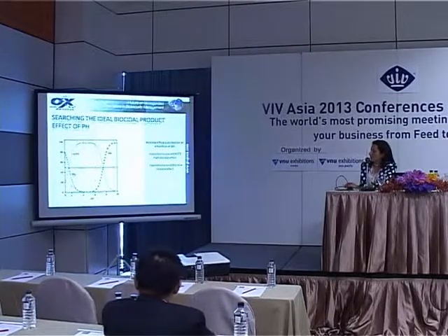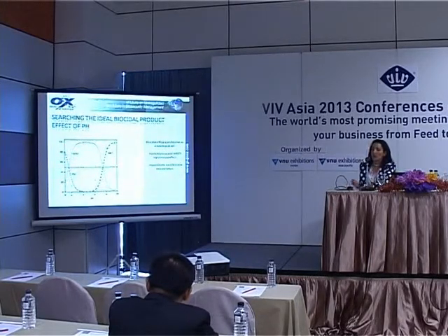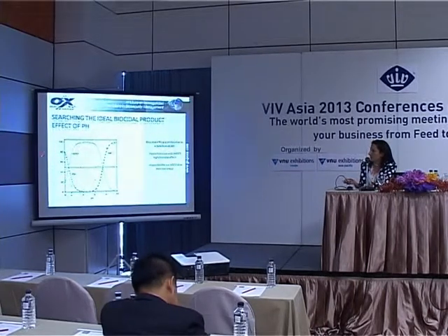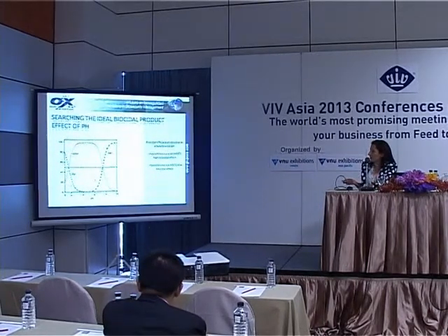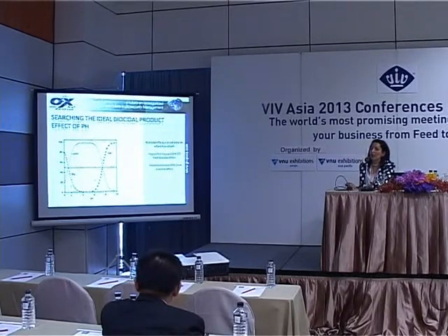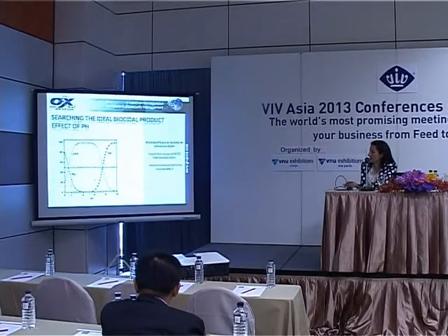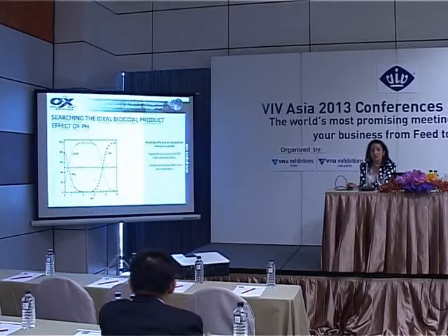If we have pH up to 7.8 approximately, the highest formation will be hypochlorous acid, which has a high biocidal effect, so we won't have problems. But if we have a pH over 7.8, the formation of hypochlorite ion is increasing quickly, and then we do not have a high biocidal effect.